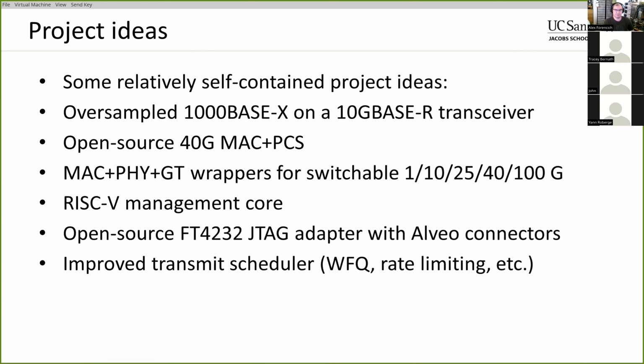The problem with PicoBlaze is that it's very specific to Xilinx devices. I think the last time I looked at the PicoBlaze, it's manually constructed from Xilinx LUT primitives, so it's not very portable across different FPGAs. So using a more device-independent RISC-V core would probably be more flexible from that standpoint.